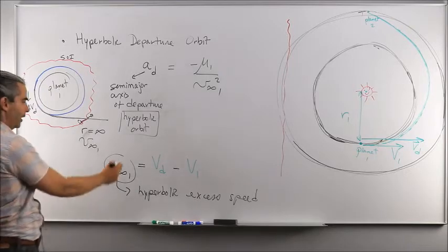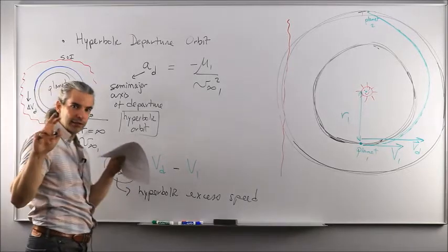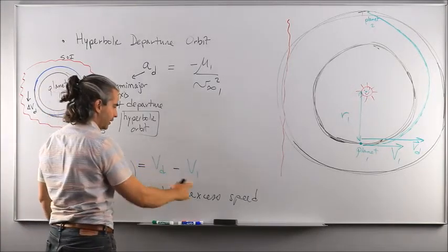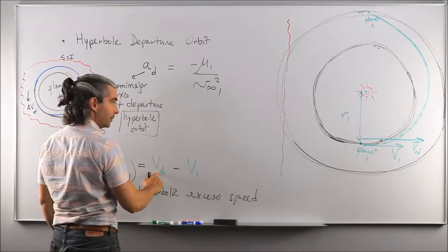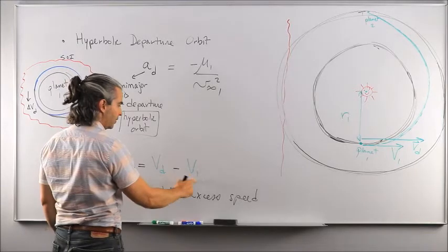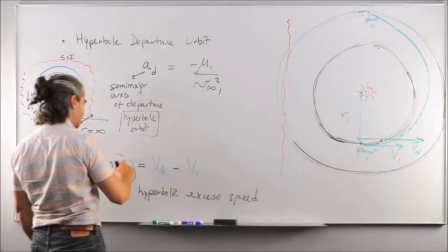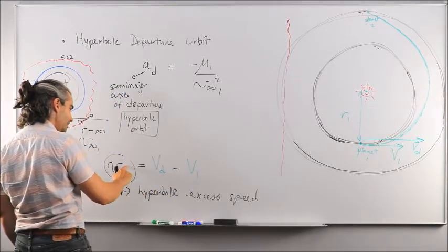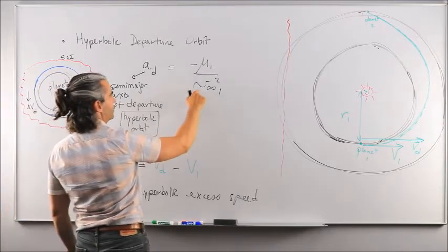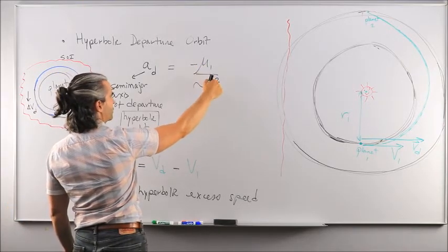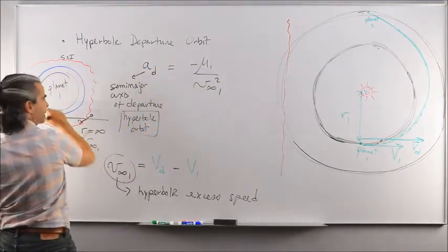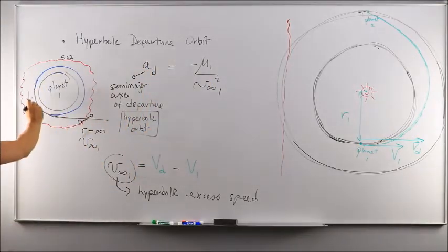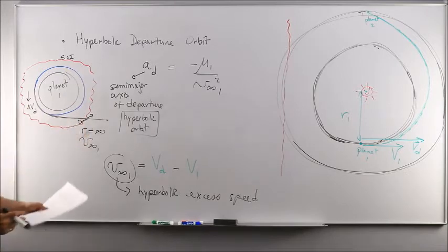Okay, so you take this value you got by doing a fake delta V from the heliocentric system perspective. So the speed along the big elliptical transfer orbit minus the speed of planet 1 along its circular orbit gave you the hyperbolic excess speed here. Plug this back into this relationship by squaring it, and that's going to give you the semi-major axis of this hyperbolic trajectory or orbit.